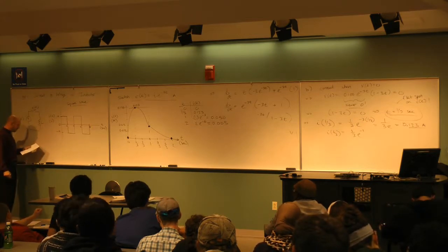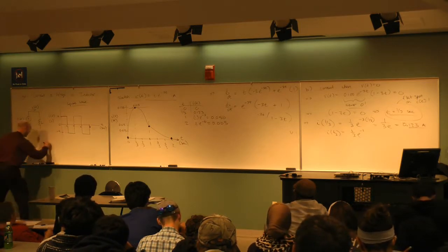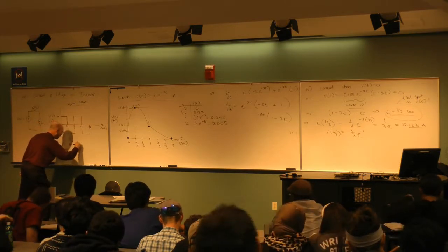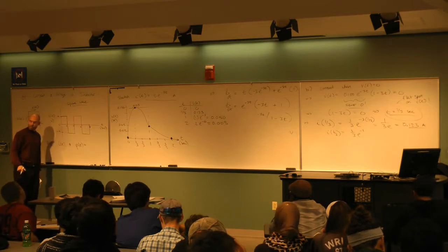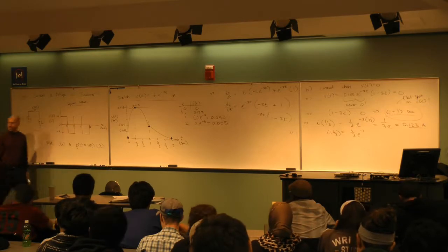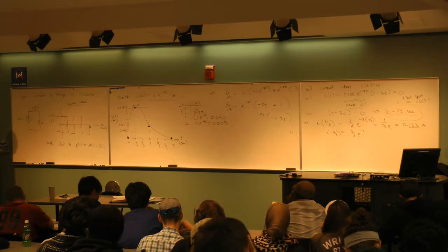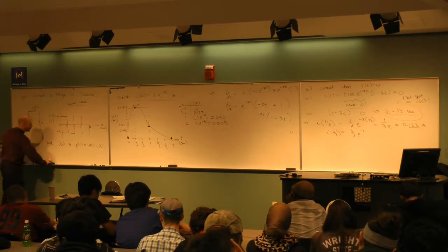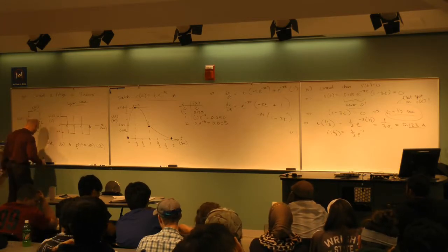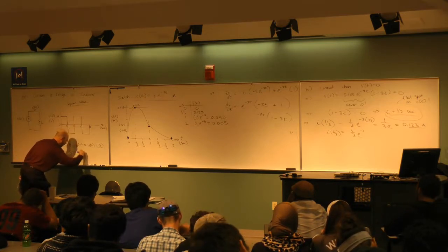The question is, what is going to be the current and also the power? So what I want to do is plot I of t and also P of t, and remember what the power is. The power is the voltage multiplied by the current. So we want to think about how do I multiply two graphs that don't even have an equation? Because that's what we're going to do. Plot I of t and P of t. And of course we're going to need a number for the L. Let's say L is equal to 500 millihenries.